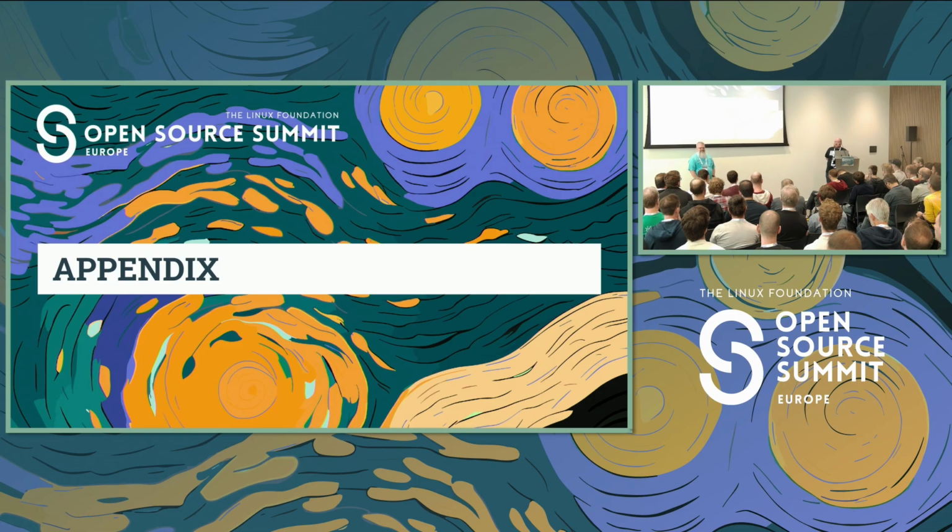I just took the BeagleBoard image for the BeaglePlay from their website and flashed it to the MMC, and said that was my baseline. That's the U-Boot version I'm going to use. That's the rootfs I'm going to use, and I didn't worry about it from then on. After that, it was all TFTP. Thanks. But it should be possible to write enough to flash eMMC as well.